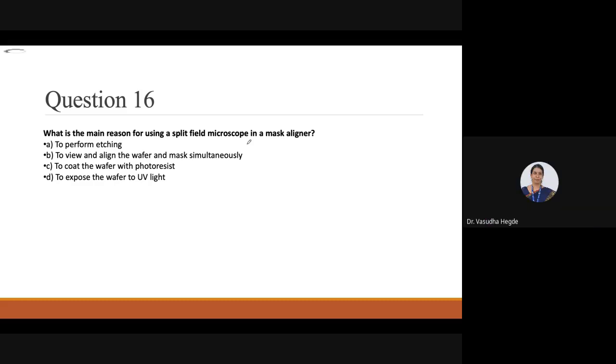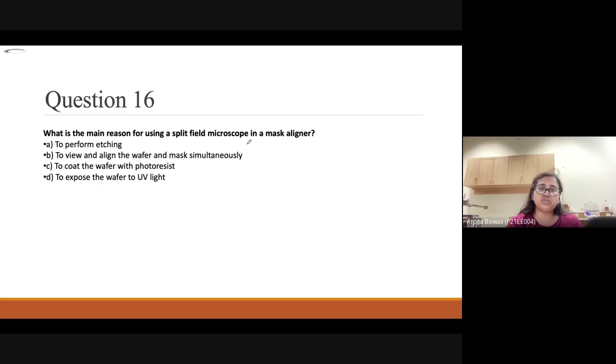In dry etching and wet etching, we have already discussed that in wet etching there is anisotropic and isotropic etching. In isotropic, etching happens in both directions, so we can face the undercut issue. In anisotropic, this type of structure is present, with an angle also.